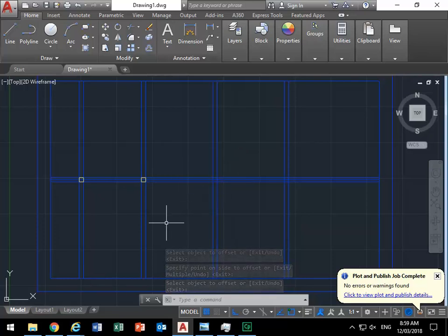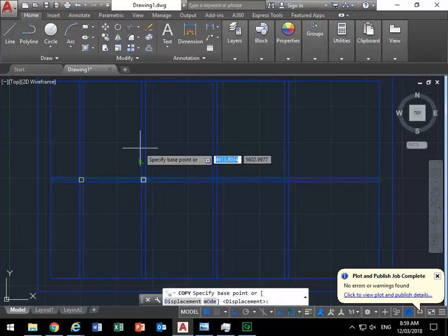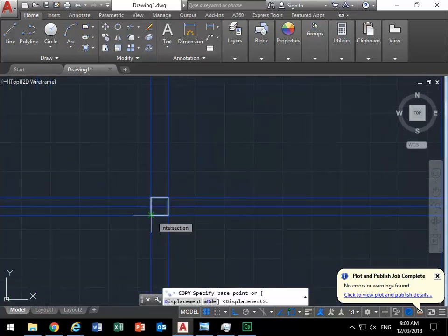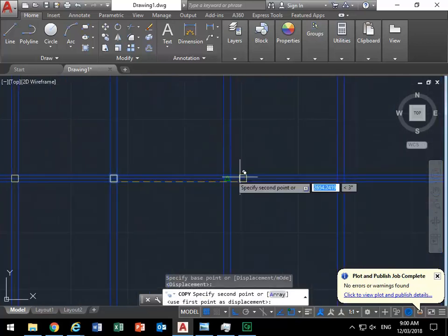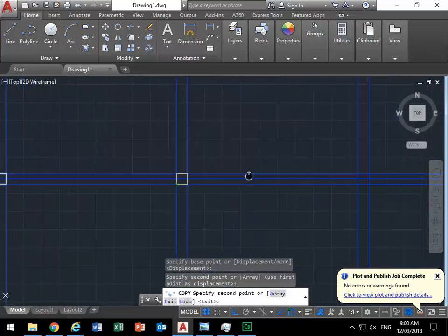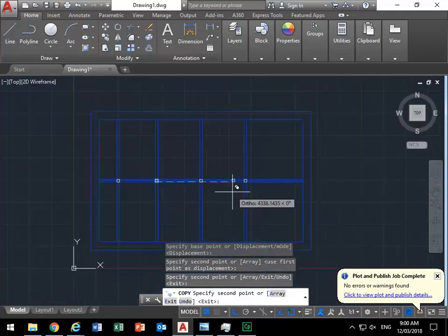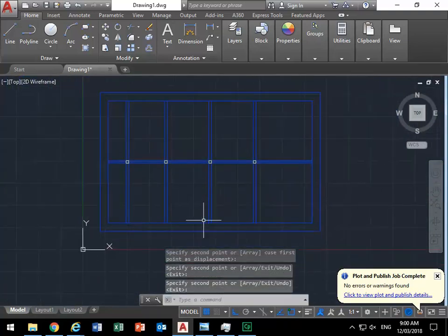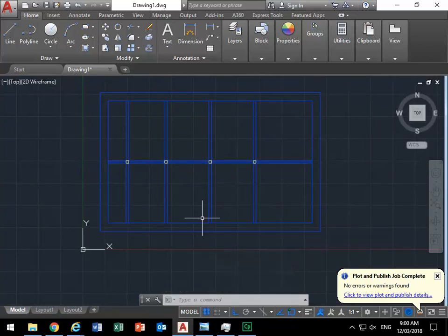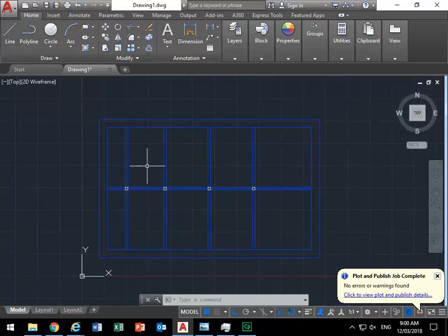Okay, so you can see then that I've put in these construction lines. And now, if I go to copy the rectangle, I've selected it first, and then I can click copy, and then simply snap to the bottom left corner, and then go along snapping to the intersection at each of these construction lines. And that's almost as quick as typing in the measurements using copy, but there's probably less chance of error there if you put the construction lines in like that.